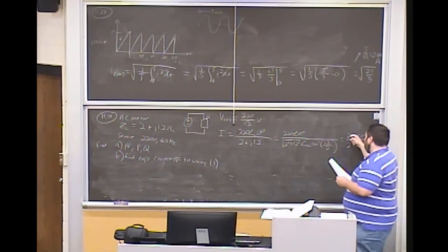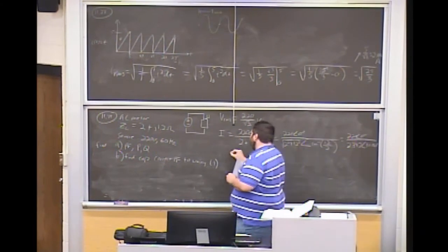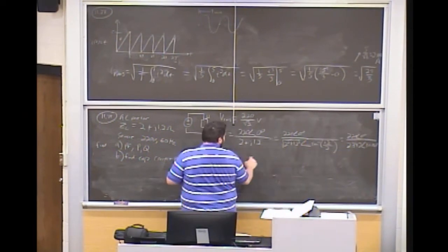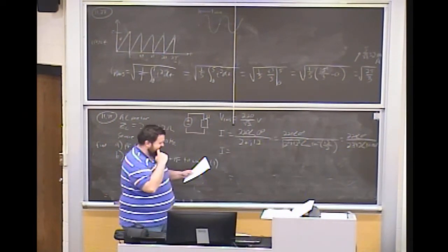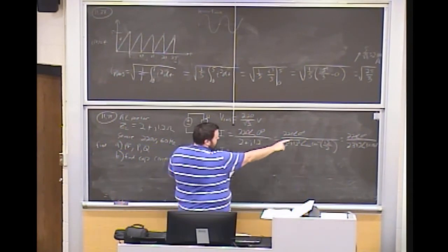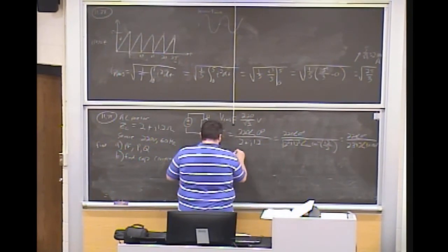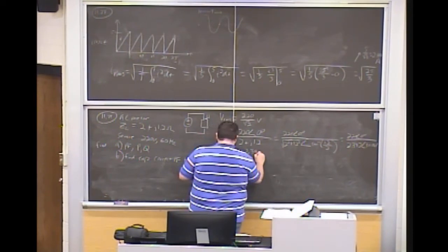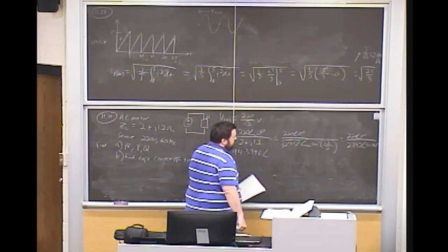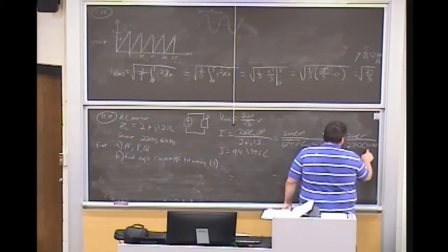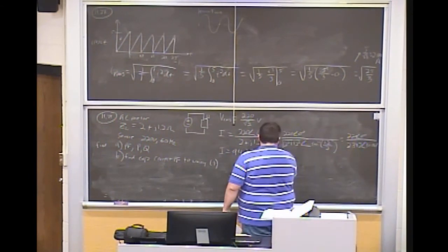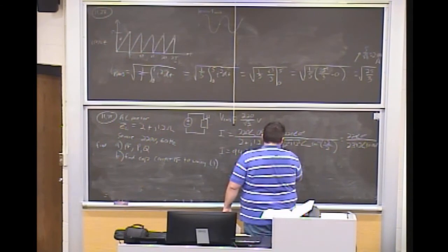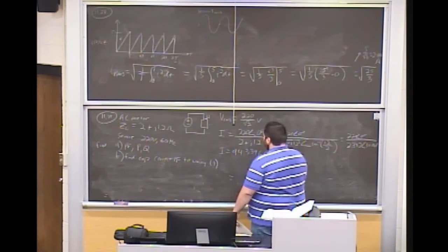Now we can go ahead and divide these two phasors. Divide the magnitudes there. So 220 over 2.332 works out to be 94.3396. And just subtract the angles, so you get a negative 30.963 degrees.